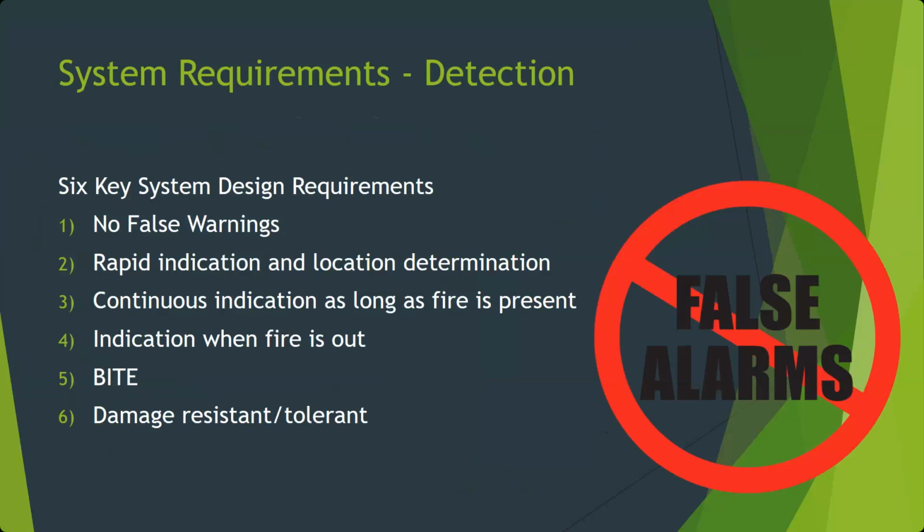Okay? When we did the lab looking at the smoke detectors in the cargo bay, remember every one of them had a cage over the front of it. Those have to be there. That's not just, oh, we want to make it less damage to our smoke detectors. It is, the FAA says you've got to protect them with a cage like that. So if you throw a bag or a box into it, it's less likely to damage the smoke detector. Okay.